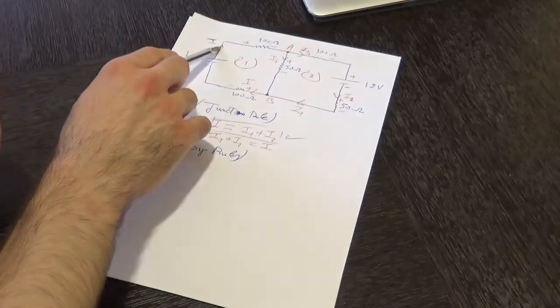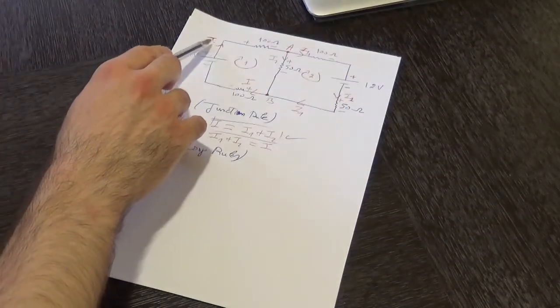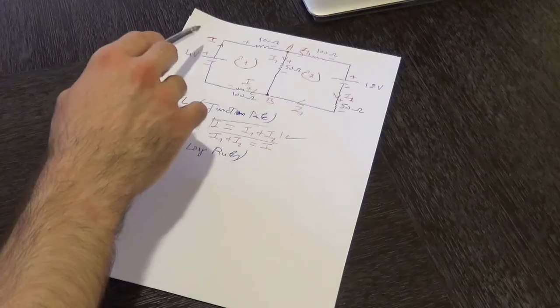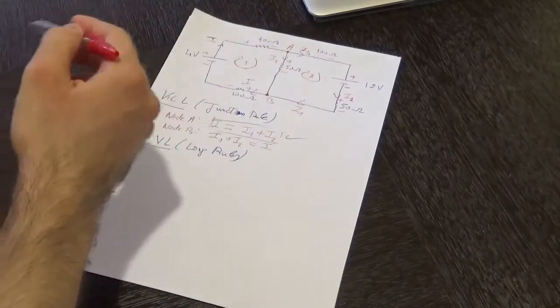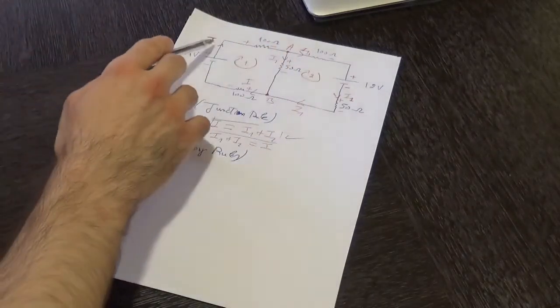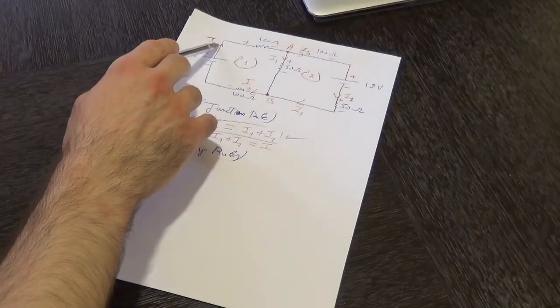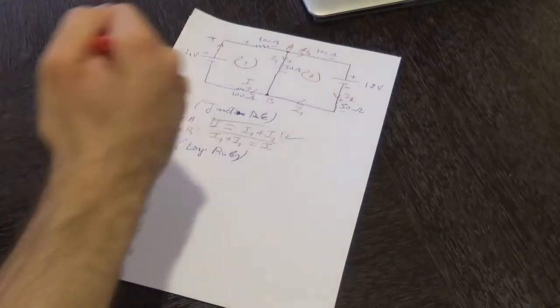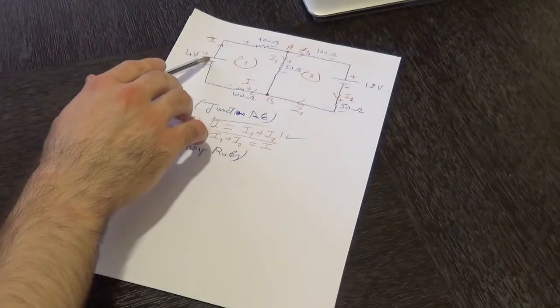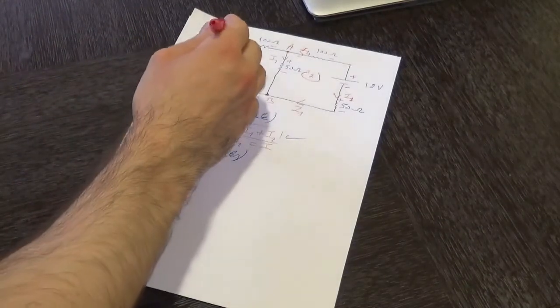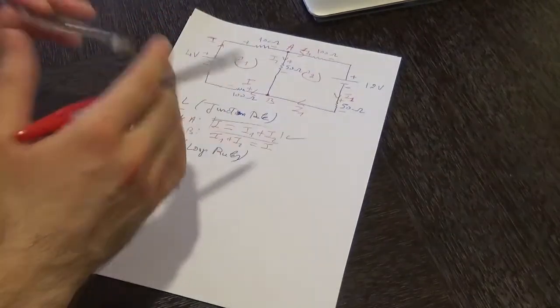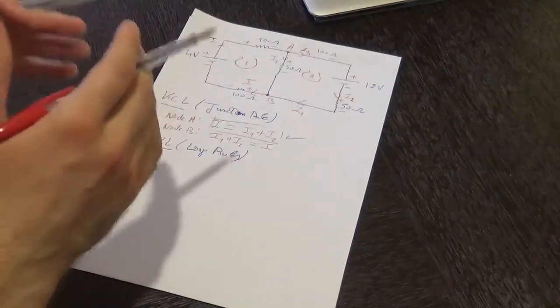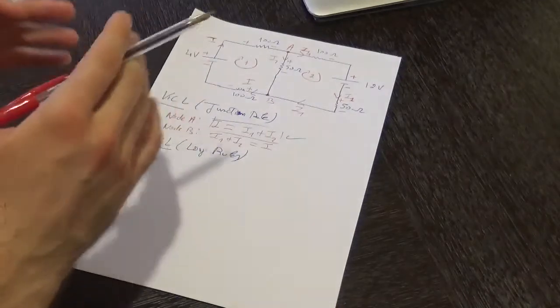In a similar manner over here, let's say after determining a value for I, that value of I has an associated negative sign. That implies that the direction that we have chosen for that main current was the wrong direction, and we have to flip it. So instead of having that main current coming out of the positive terminal, it's going to be entering into the positive terminal. So in brief, our choice for the conventional current, especially when you have two batteries in a circuit,